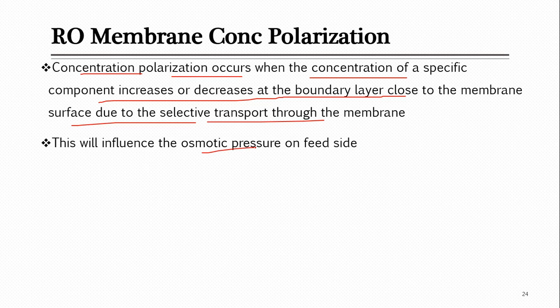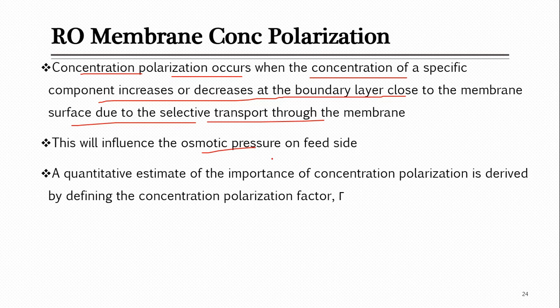Because we have seen that the osmotic pressure across the membrane is highly dependent on the salt concentration. If salt concentration is increasing inside the system, that will increase the osmotic pressure, and membrane performance will decrease. So it is important to calculate concentration polarization. There is again a derivation for this, a quick derivation, but we will look at the final expression that can be used for calculation of the concentration polarization factor.